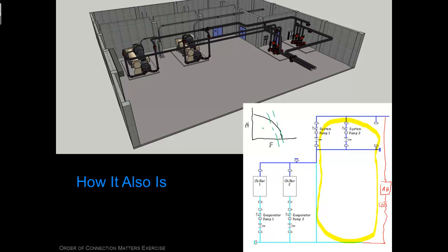My first variable flow system was a variable volume air handling system, and I designed it in the late 80s. At that point in time, for a 40 horsepower motor, I chose an eddy current clutch as my variable speed mechanism, because I could get one of those for about $20,000, whereas a variable frequency drive would have cost me about $50,000 and also would have been about twice the size of the gray box here running that chiller.